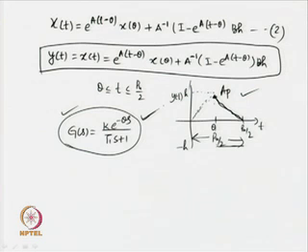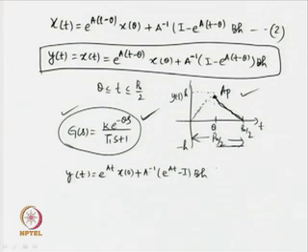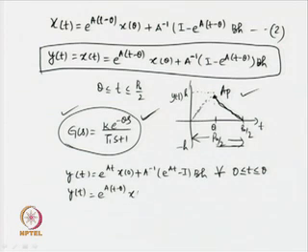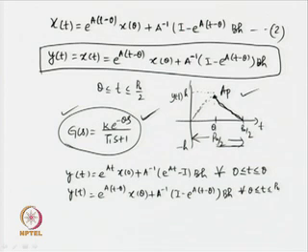So, finally, let me summarize both the equations I have obtained for the typical oscillatory output. y(t) = e^(at) x(0) + a^(-1)(e^(at) - I) b h for the time range 0 ≤ t ≤ θ, and y(t) = e^(a(t-θ)) x(θ) + a^(-1)(e^(a(t-θ)) - I) b h for the time range θ to Pu/2.